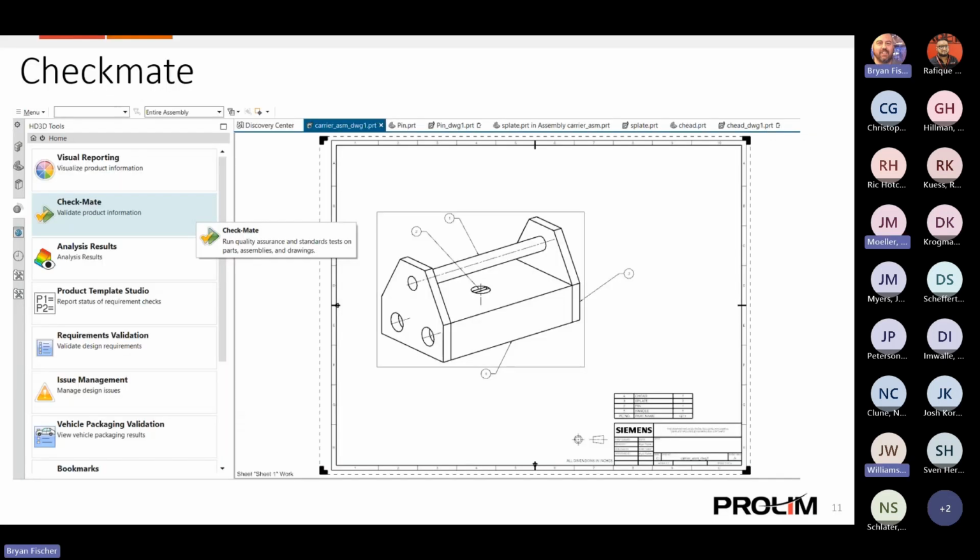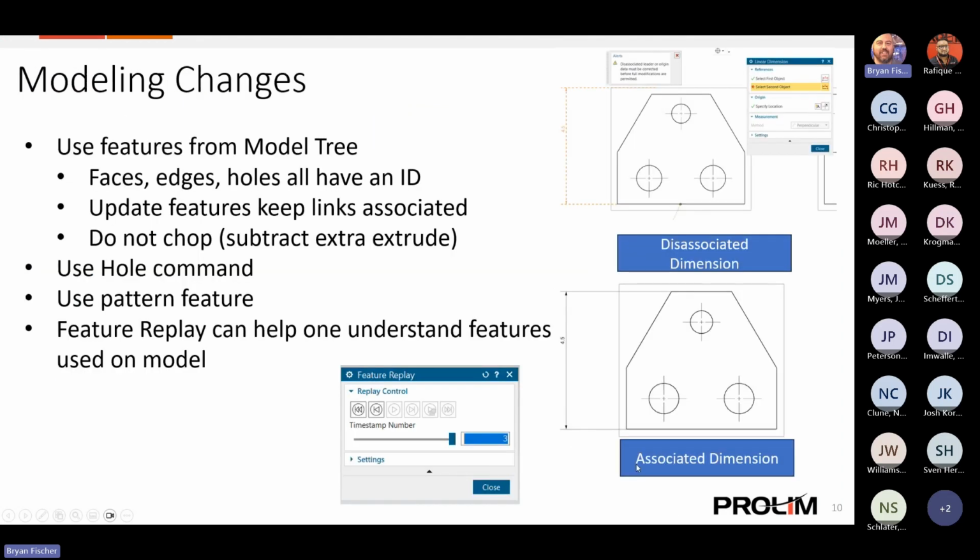With that being said, I did want to show something else in here before we get to that question. Yes, Joe. A user can delete the entire history and make it an object only, so that synchronous can then be used. I don't suggest it, but correct, NX does have that ability to unparameterize everything.